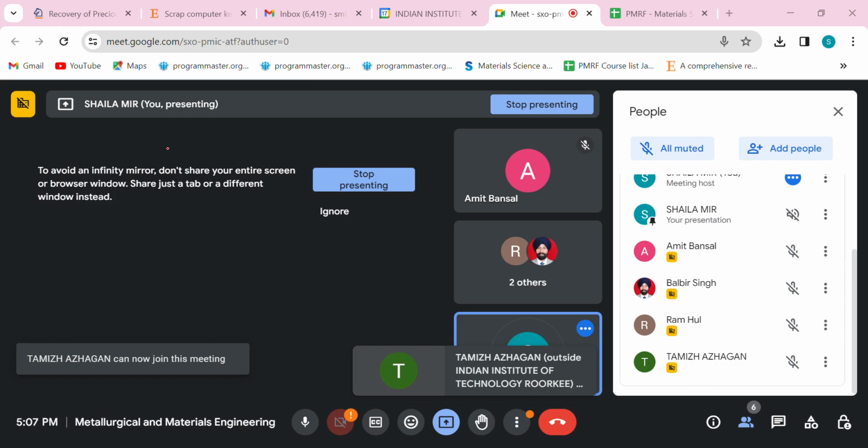They might have some other composition changes. This Nd2Fe14B remains mostly in your hard disk drives or in your wind turbines. Sometimes they also use some Dy, which is dysprosium, or some dopants of, say, gadolinium. So depending on what kind of application it is, your mobile phones also have speakers. The speakers in your mobile phones also have rare earth magnets. They have some gadolinium in them. So, ma'am, do you mean we are using hard magnets in them? Yes, yes, they are permanent magnets that have been used.